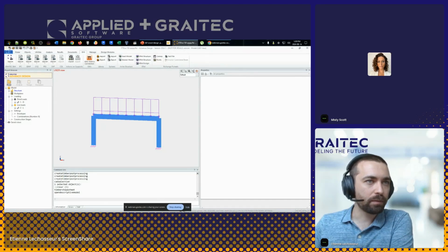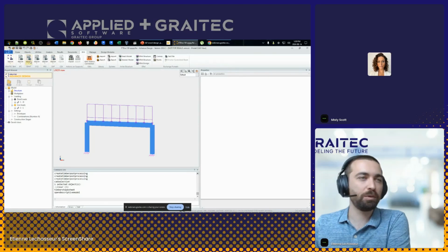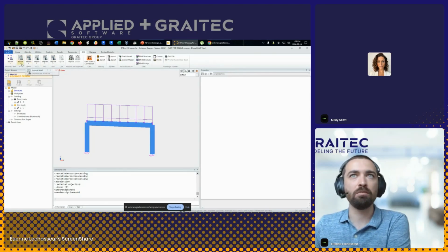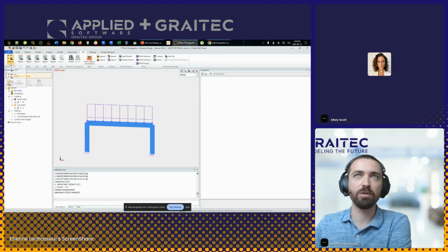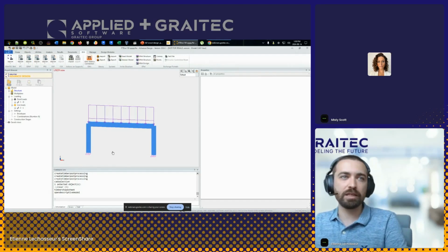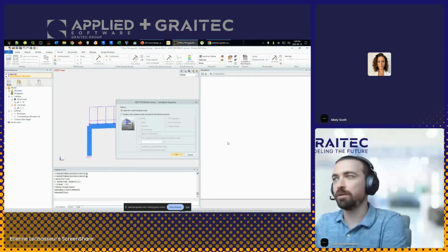And then he also asked, can it be entered into a BIM or a quantity estimate takeoff of design? Yeah, so it would depend on what format your other software supports. Most likely it's going to be IFC. But if you were working, for example, with Revit, you could be using our Power Pack, which would give you a better transfer. But we do have many different ways you can transfer it to different software. And for quantity takeoff, it's also possible to do it straight in Advanced Design. So it's actually a fairly popular question.